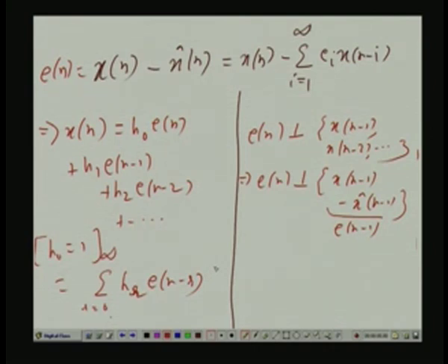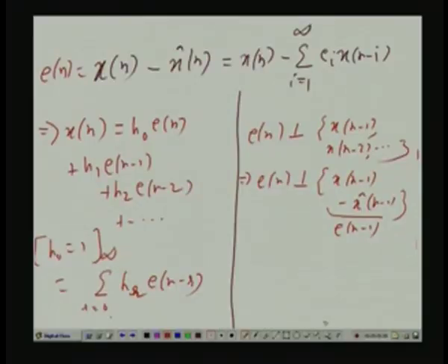In that case, can I now approximate that infinite impulse response causal IIR filter by a rational model H z, where H z is a ratio of two polynomials in z, numerator polynomial, denominator polynomial. If it is having both numerator and denominator polynomial, we call it ARMA or autoregressive moving average model, or equivalently pole zero model. Otherwise, we have the autoregressive model, that is AR model, or we have the MA model, that is moving average model. In our case, we will be considering the AR model. So, now we have got a full justification for going for this modeling process.